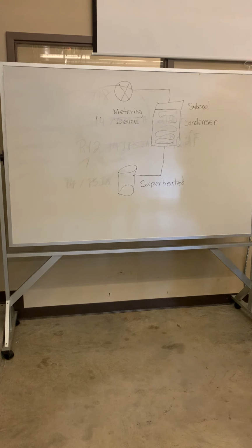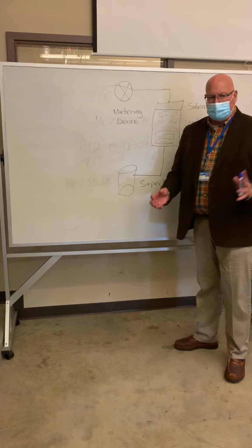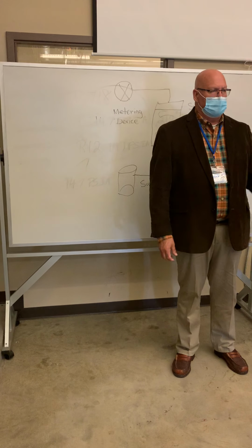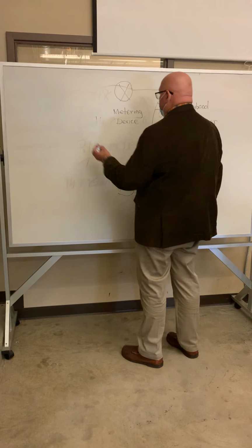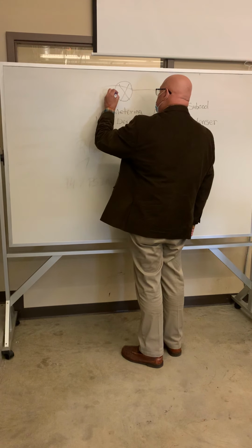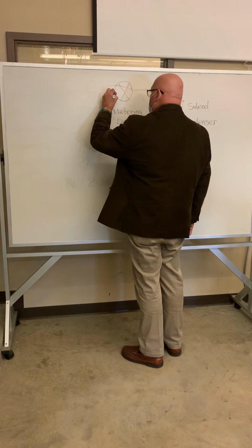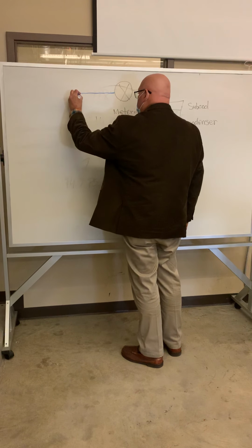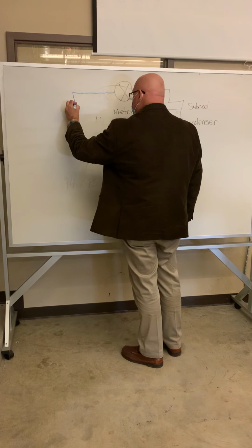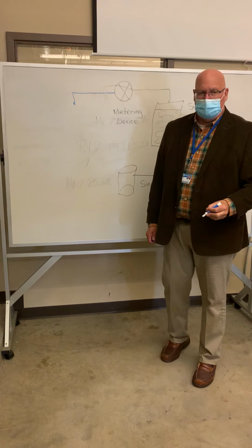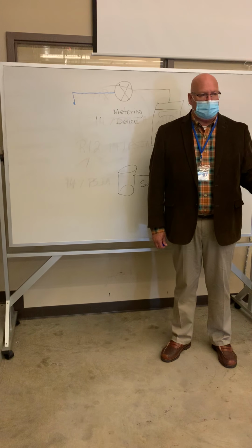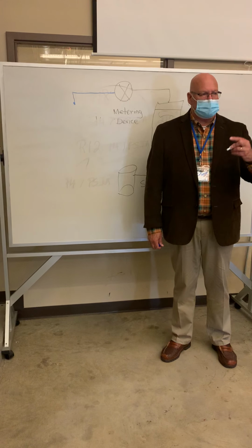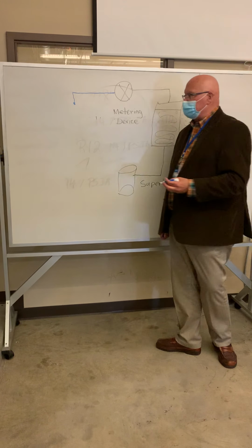And one of the things we do when we talk about reduced pressures, remember how I said the manifold gauge is a blue gauge and a red gauge? Well, the blue gauge represents the low side, and so when we draw this, we usually show leaving the metering device this low pressure liquid refrigerant, which is key. It's a low pressure, but it's still a liquid refrigerant. That hasn't changed. There has been no heat exchange that's gone on with this as of yet.